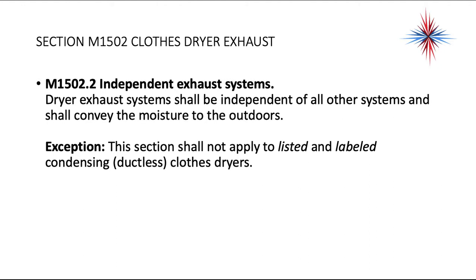Dryer exhaust systems shall be independent of all other systems and shall convey the moisture to the outside. Dryer exhaust systems have a problem with humidity, moisture, and lint. They're considered a real fire hazard in reality. Dryer exhaust systems shall be independent of all other systems. In other words, you cannot mix bathroom and kitchen exhaust with dryer exhaust.